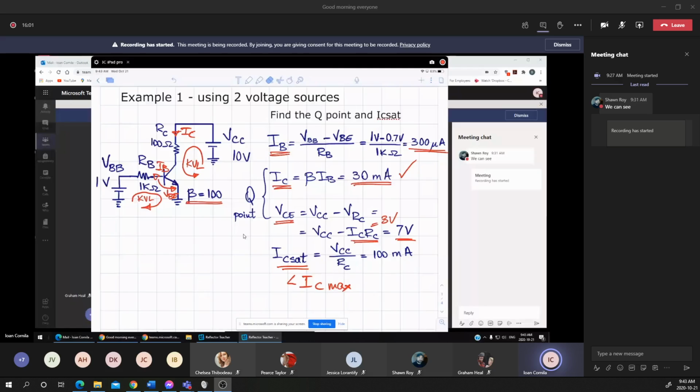As I mentioned, usually it's about 80% of the maximum current. Again, that maximum collector current can be the typical, the minimum, or the maximum. If all three currents are given, I'm choosing the minimum current.